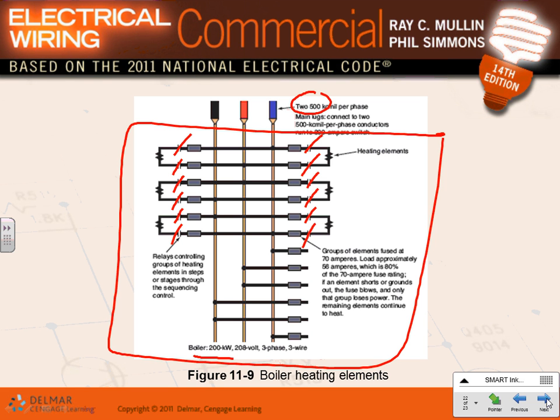Now for the building, Joe, the building that you're doing right now, see all these... anybody remember what the circuit was? I can't remember the actual size of the boiler. Anybody has the riser? What's the amp size of the boiler circuit? I think it's 800, yep, 800 amp, right here. So this is coming actually from an 800 amp. 800 amp at what voltage? 208/120. An 800 amp feeder is feeding just the boiler.